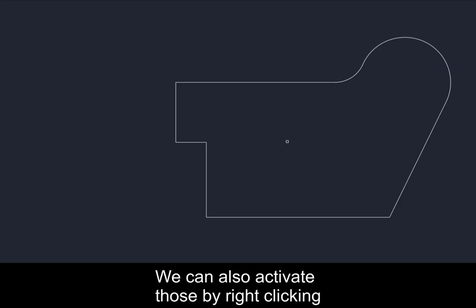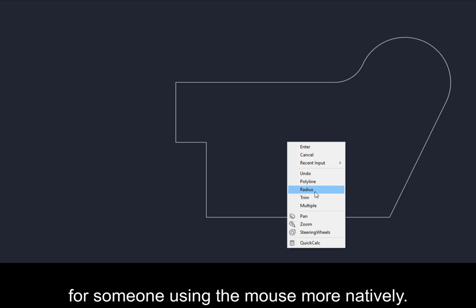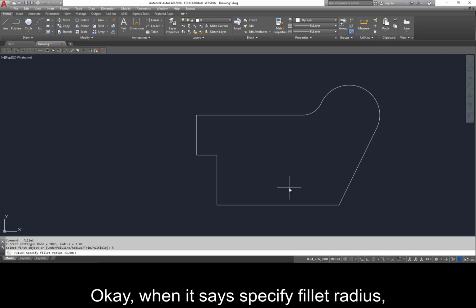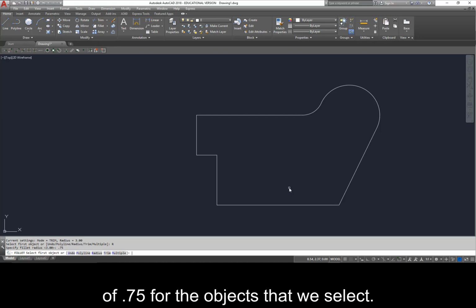We can also activate those by right-clicking and going to radius. These are the options that are available down on the command line, but available for someone using the mouse more natively. When it says specify fillet radius, instead of 3, we want to make it 0.75, hit enter, and now we have a fillet radius of 0.75 for the objects that we select.